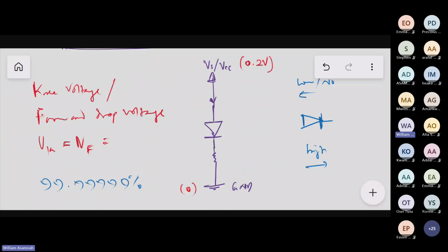For silicon, diodes are very good. They are temperature stable, right? They don't behave erratically with temperature. At first, germanium didn't need that much purity. Germanium's purity wasn't very high, so it was very easy to get a germanium diode. But the problem is that germanium was very sensitive to temperature. The moment temperature changes a little, its behavior will start changing. For instance, the knee voltage.